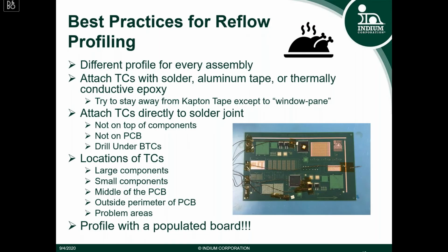Reflow profiling. We started to talk about reflow profiling in the beginning of the presentation. Reflow profiling is when you hook up thermocouples to your assembly to read the temperatures that the solder joint is seeing during the reflow process.